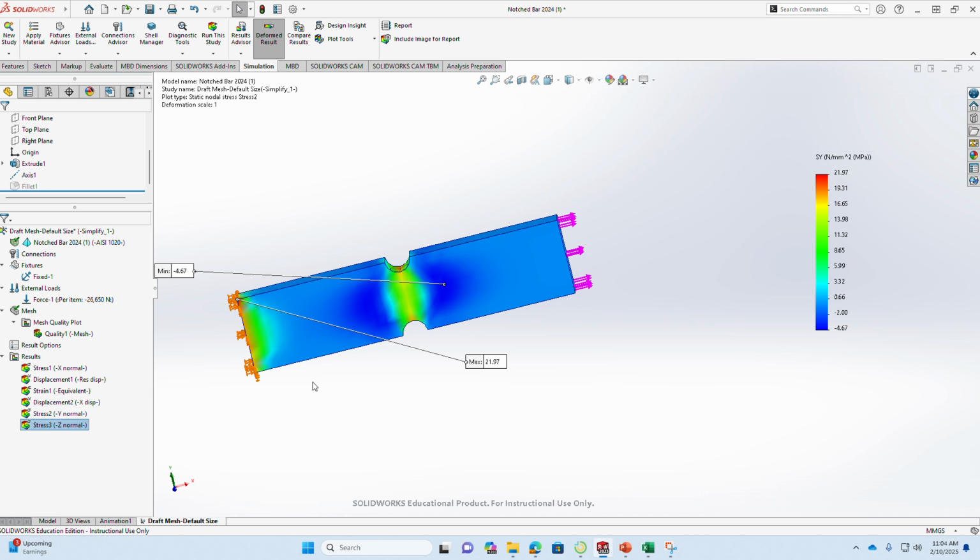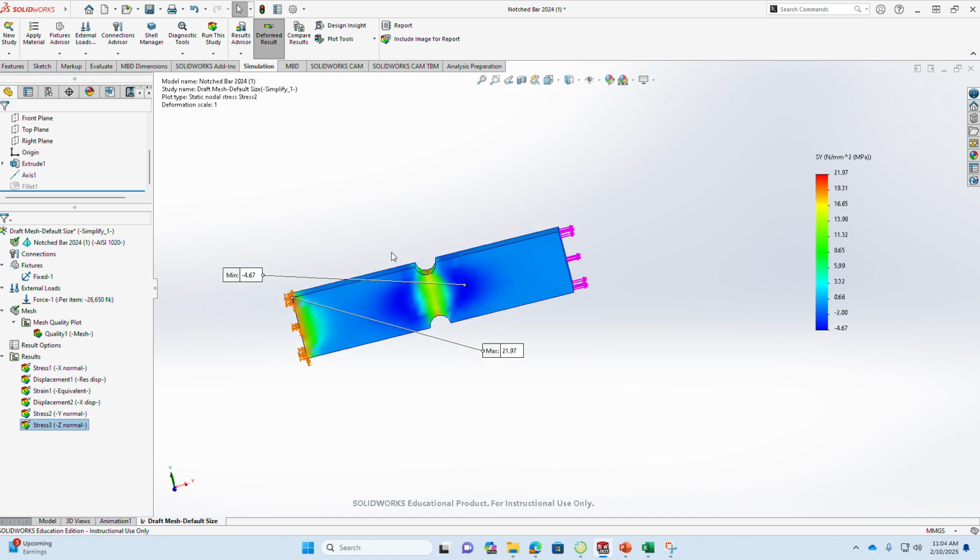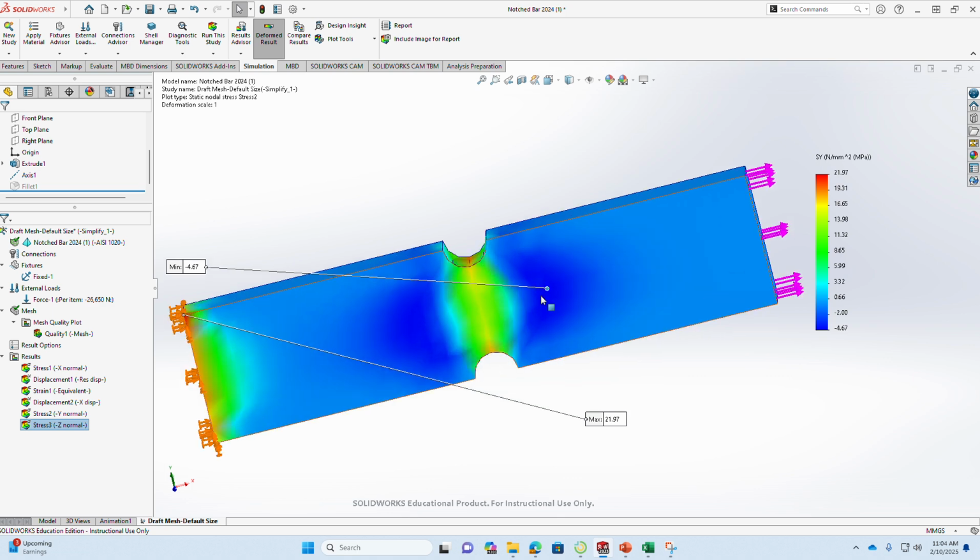Okay. Now you can see here, interestingly, that for your y and z-axis stresses from your hand calculations, you have no idea of what the y and z-axis will be, right? But from the computer generated values, because we have used a full 3D analysis, you can also see what the values along the y and z-axis will be because of the Poisson effect.